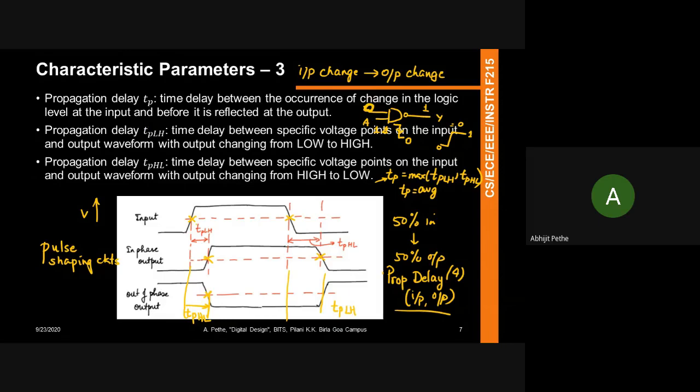Okay, Manthan, let me repeat. Whenever you measure time differences or time delays, you need 2 points. Suppose I have a pulse which looks like this, and I have another pulse which looks like this. How do I define what the delay between the two pulses is? Normally I take a common reference point, say 50% of the voltage, and I measure the time difference between these two and say this is my delay between the two pulses. I could have also taken this point and this point, or this point and this point, but generally the convention is to take the halfway point.